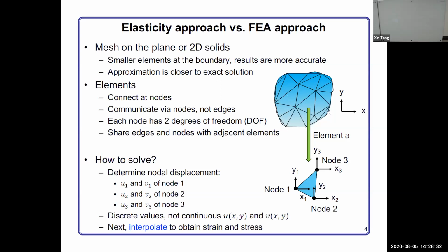For this geometry and solids, we will put bigger elements or elements with coarse size in the center, because in the center the geometry is more simple. But put denser elements, smaller elements, more elements at the edge, at the boundary. Because at the edge and at the boundary of this object, the shape is more irregular. So you want to use more elements to cover all of them correctly, okay?